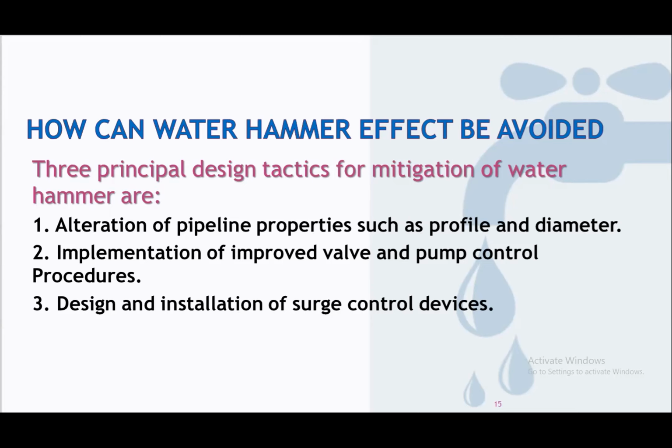And the second point, improving the process of pump control and valve operating conditions. Of course, as much as we can, we have to avoid the process of pump power failure and pump startup. And of course, the process of opening and closing of the valve has to be gradual, as I said before, not a sudden valve opening or a sudden valve closing.